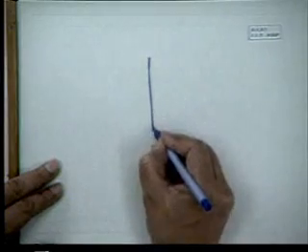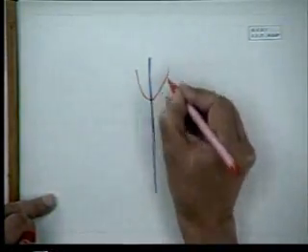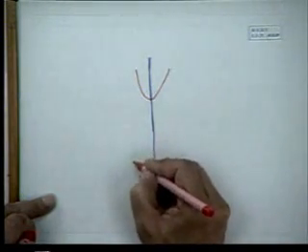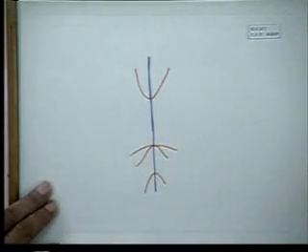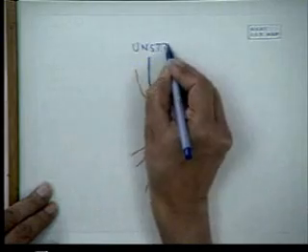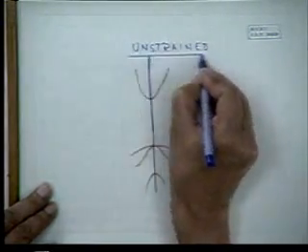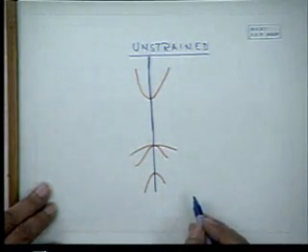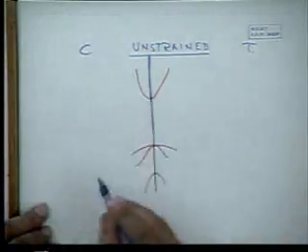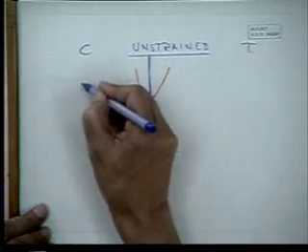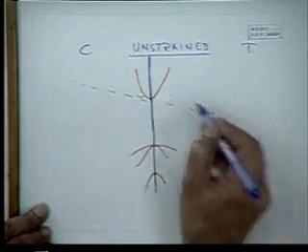To repeat, overall the effective strain, this is what I discussed last time. Suppose you have an unstrained layer, where here's a conduction band, and suppose this is the heavy hole band, and this is the light hole band, and this is the split off band. One easy way of remembering this is unstrained, and we'll talk about compressive and tensile. Okay. Now we know under compressive strain the band gap increases. So as a result, this band goes something like this.